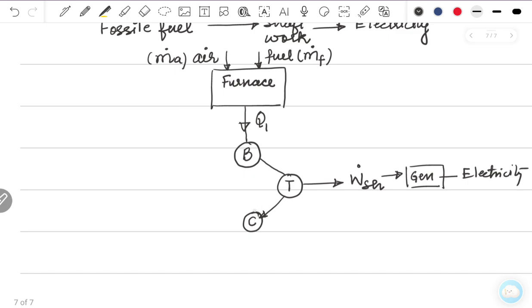In general there is a cooling tower, you might have seen, and that energy is discharged there and ultimately to the atmosphere. Then this condensed low pressure water is transferred to a pump which increases the pressure of the water to match the boiler, and then that water is fed to the boiler.